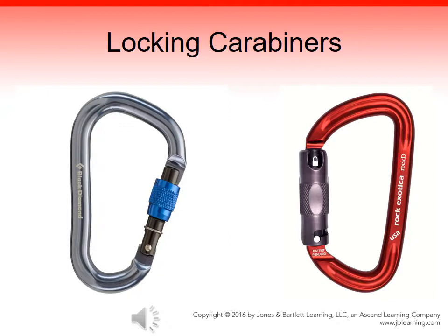A spring-loaded sleeve called an auto lock could be a manual locking sleeve, requires a quarter turn to unlock. It should be used with caution because some versions can open very easily. Notice the padlock icon is visible when the gate is locked. An unlocked padlock or a skull and crossbones is visible when the gate is unlocked.